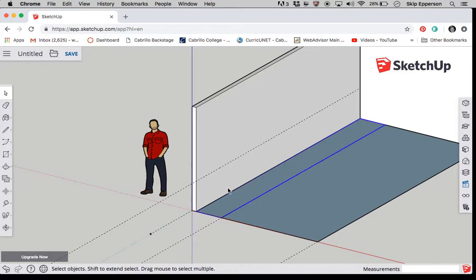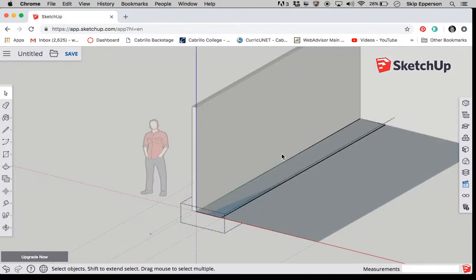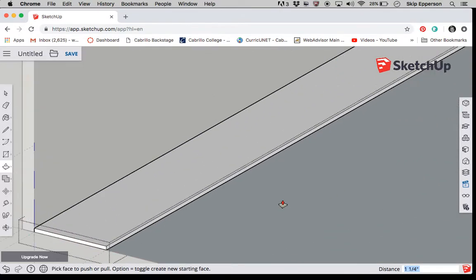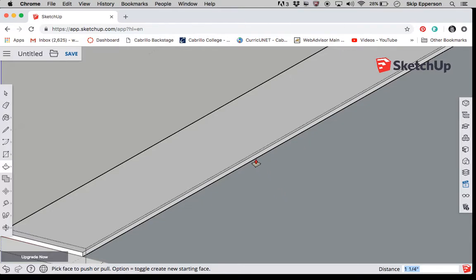It's very flat. It's a group. I'm going to double click on it, and I want to build my countertop. Give it some thickness with the push-pull tool. Hover over it and push up. Let's say the countertop is 1.25 inches thick. So I start it, now type in 1.25 inches, hit return, and it says I'm that thick there.